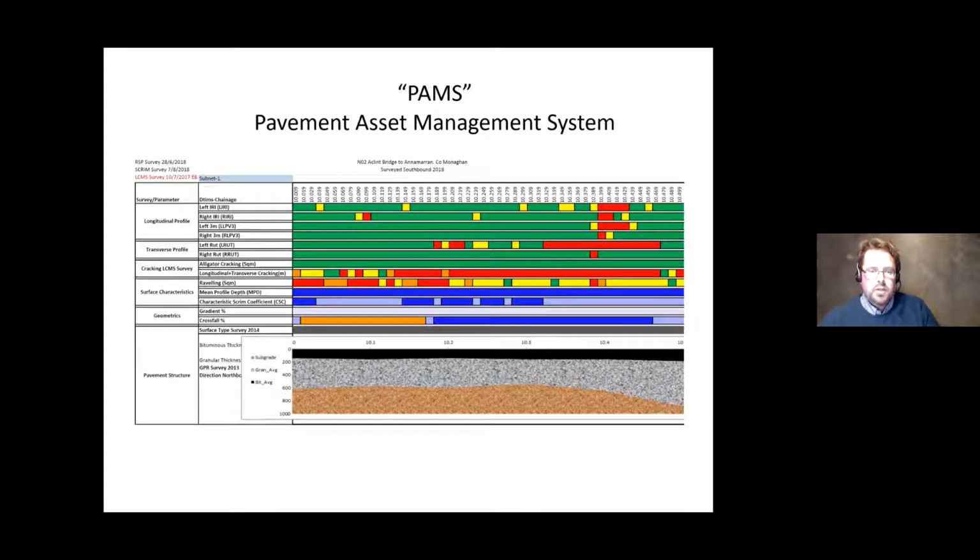Generally, when you're looking at these, you'll look at the chainage across the top, which is deep chainage. If you're working on a site-specific scheme, you can correct that to your own site-specific chainage. Mark in your chainage identifiers, your landmarks, your junctions, your houses, your roads. Make yourself familiar with how this lies on the ground, so that when you go out looking for these distresses, you know where you're looking and you know what's happening.